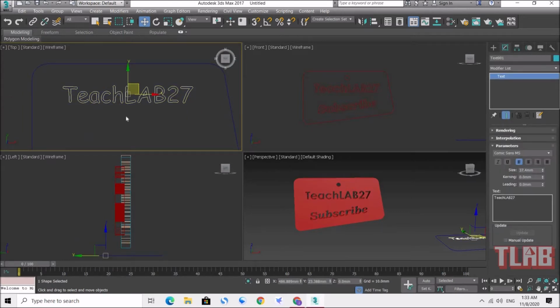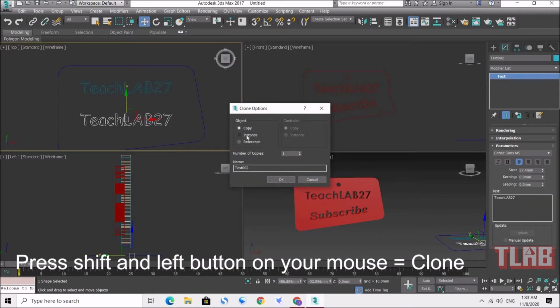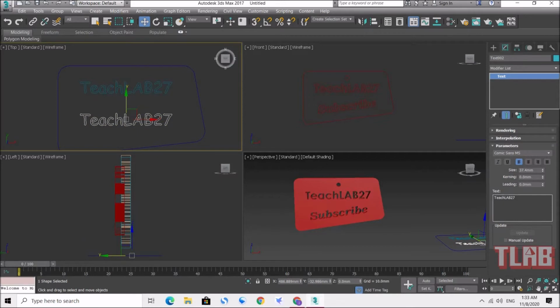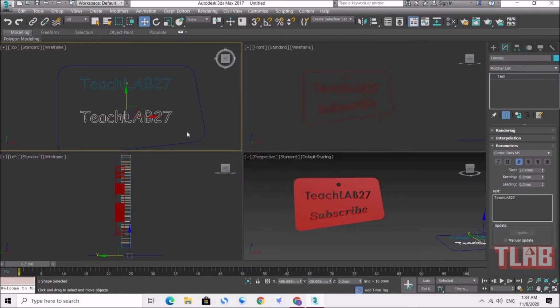Okay, how about the second one? This one is easy. You still remember how to clone. Just press Shift and move down. But this time remember, don't use Instance, because with instance, if you select this one and then change the wording, you can see they will change together. So remember. If you click undo, you cannot undo this, which means you need to type in again. So Teach Lab 37. Now press Shift, move down, and use Copy because it is different wording. This one I just put Subtract.